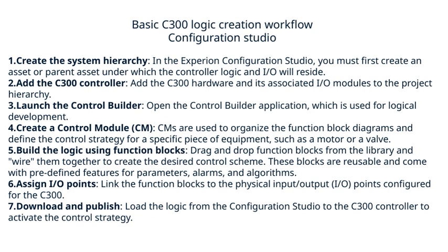This workflow, creating a hierarchy, adding hardware, developing logic with function blocks, linking I/O, and then deploying, is fundamental to implementing reliable and efficient control systems with the C300.